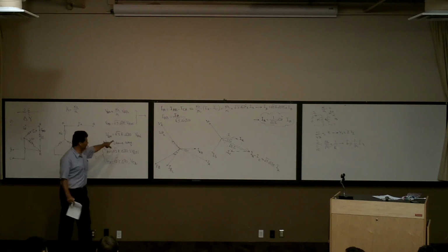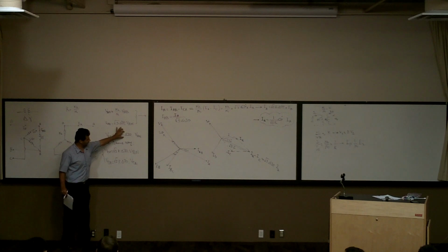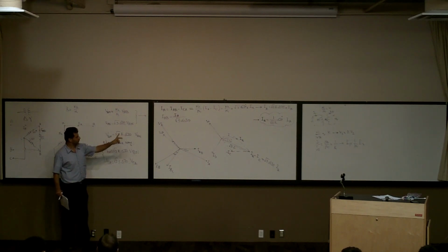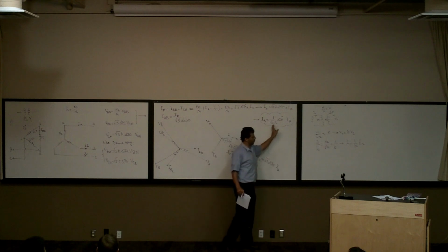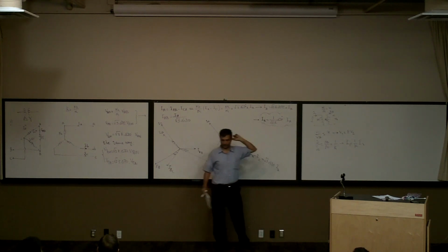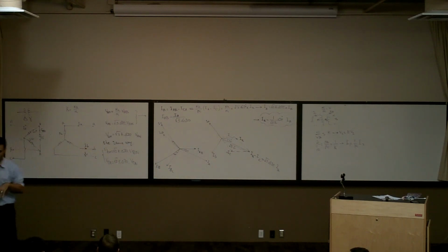No, sorry. The only difference is the angle, so the scalar part is exactly like a single phase transformer. The square root of 3k here for the voltage conversion, 1 over the square root of 3k for the current conversion. But the angles, they are the same. See, 30 degree, 30 degree. So this is how you convert the voltage and current from primary to secondary and secondary to the primary.